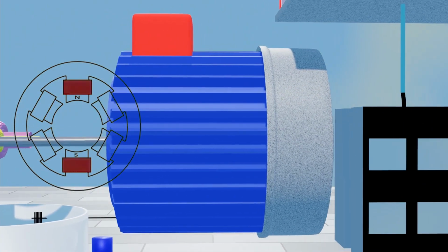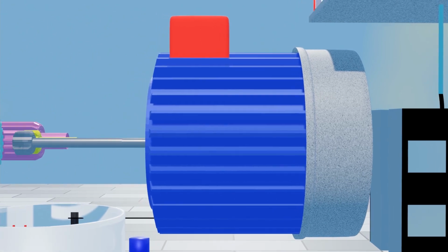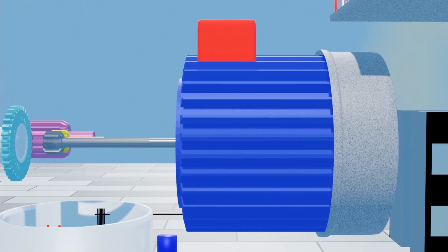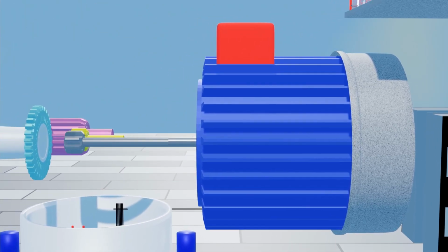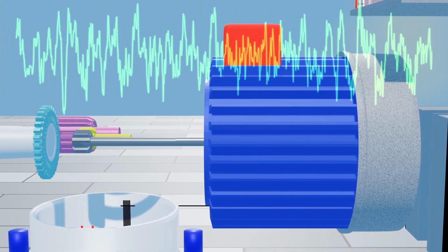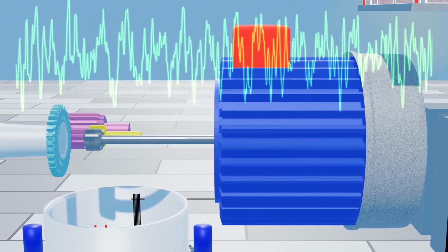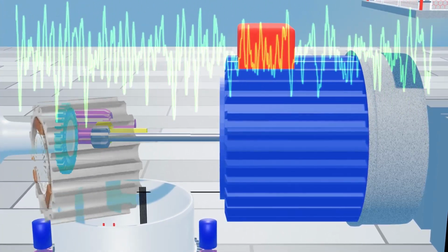The speed of the shaft can be made high by using a gearbox assembly, but we cannot make the shaft speed constant. There may be fluctuation in the shaft speed because of the wind speed. So the speed of the rotor also varies, and this variation affects the frequency and the voltage of the generated electric power. To overcome these issues, we normally use an induction generator for this purpose.